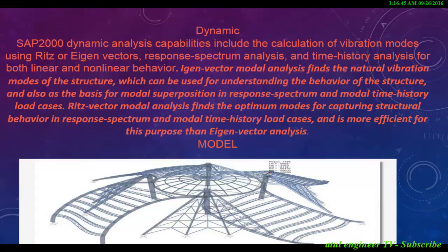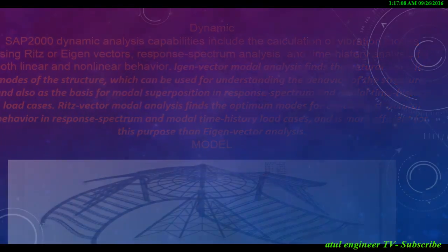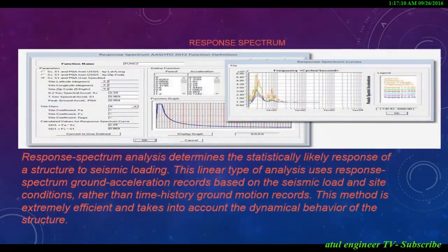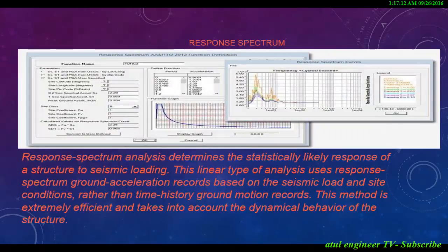Dynamic. SAP2000 dynamic analysis capabilities include the calculation of vibration modes using Ritz or eigenvectors, response spectrum analysis, and time history analysis for both linear and nonlinear behavior. Eigenvector modal analysis finds the natural vibration modes of the structure, which can be used for understanding the behavior of the structure, and also as the basis for modal superposition in response spectrum and modal time history load cases.